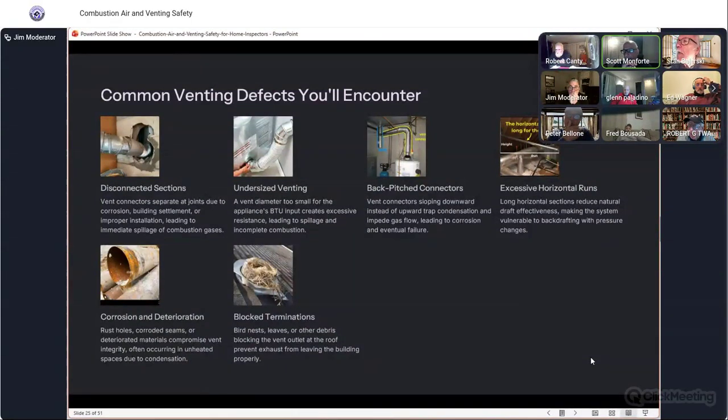Yeah, we're going to hit that again coming up, but I'll talk about it now since you bring it up. So when we started getting the higher efficiency or the condensing style water heaters, a chimney's supposed to be sized for two appliances. We'll stick with gas. We have a gas furnace and a gas water heater, and somebody needs a water heater and they put in a condensing style water heater. So now we don't have that second appliance going into the chimney.